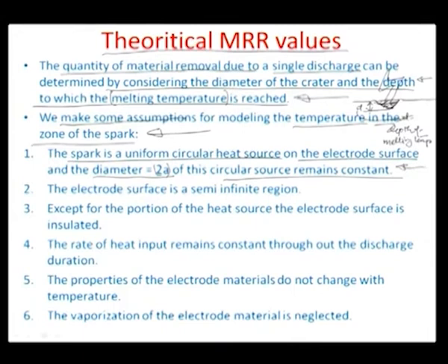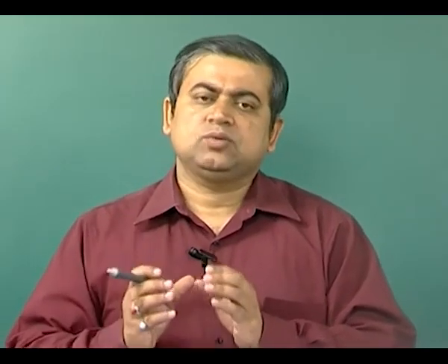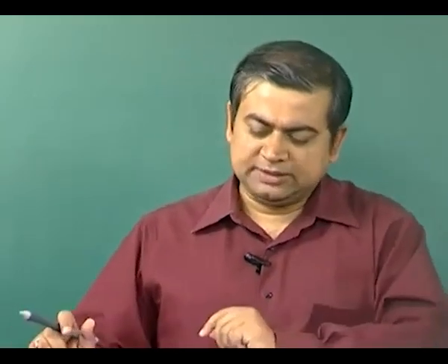So therefore we don't vary the diameter in our model, assuming that the approximate diameter of striking on the surface is the same, even though the spark may have some variability, but at least the heat transfer is taking place across a circular area if we consider the spark to be like a cylinder of constant size.